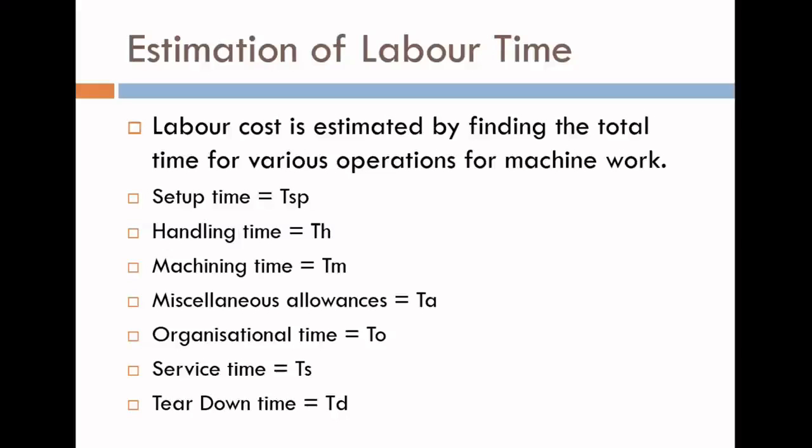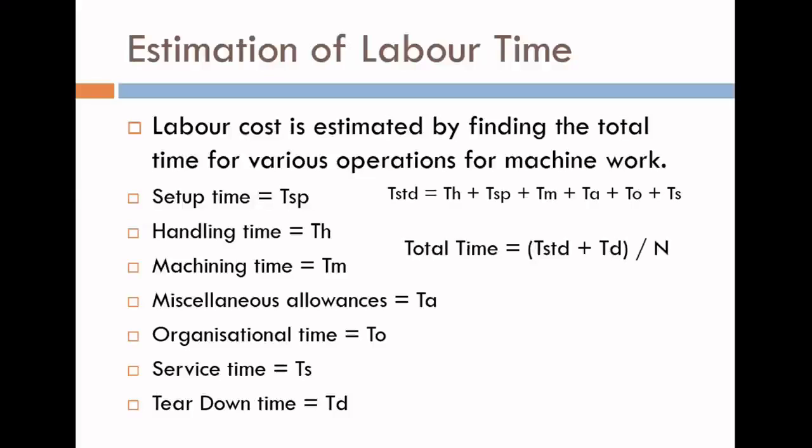The summation of the setup time, handling time, machine time, miscellaneous time, organizational time, and the service time is called standard time. And the total time we will calculate as total time is equal to standard time plus the tear down time divided by n, where n is equal to the number of work pieces.